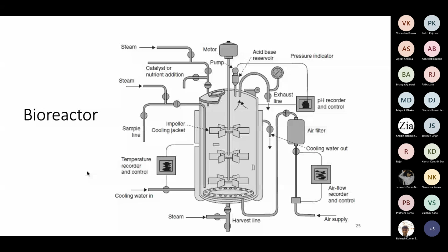Similarly, at the top you have DO monitor to monitor the oxygen concentration in the liquid. As I mentioned, oxygen concentration can be enhanced by supplying more oxygen or by mixing the stirrer to dissolve more oxygen in the liquid. So based on the requirement, it will actually have a cascade signal. So a combination of action can be activated by controller. Either it will increase the flow rate of oxygen, or it will increase little bit and also increase the rotational speed to enhance the oxygen concentration.